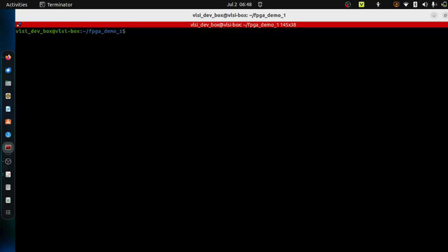Okay, now move on to the programming. So first it's icepack, and we'll pass the and1.asc file, and we'll save the data in the form of a .bin file. Sorry, and1.bin. Okay, so the implementation and the other things are actually done. Now we have to move to dumping the bitstream into the FPGA board.